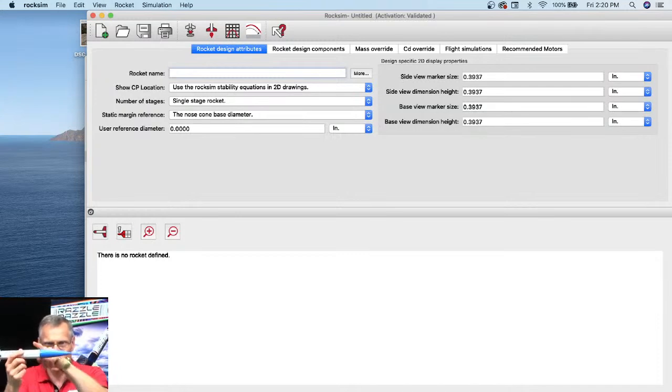On the nose cone, it will curve along the curvature of the nose cone this way, but not this way, going around the perimeter. That's just a limitation in RockSim. And that's more of a cosmetic issue in RockSim rather than a simulation issue, because they're going to sim pretty close. It's going to be in the ballpark.